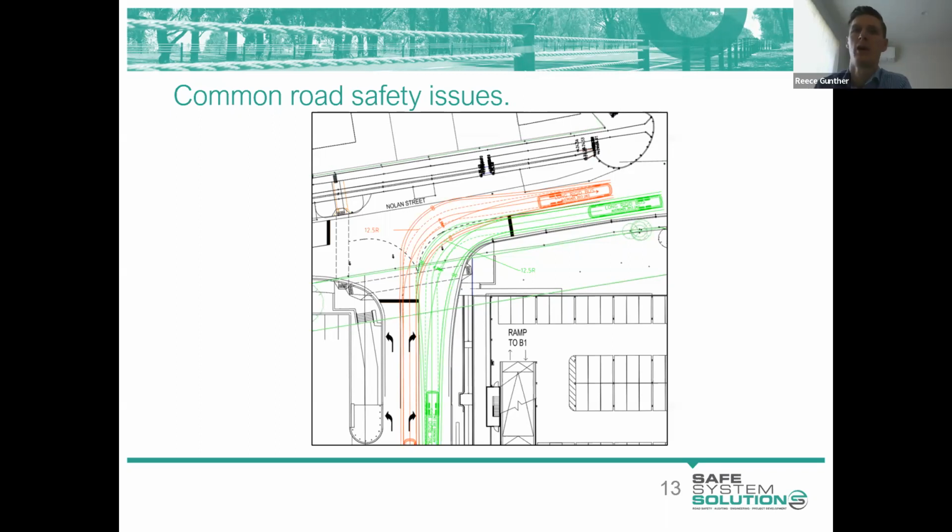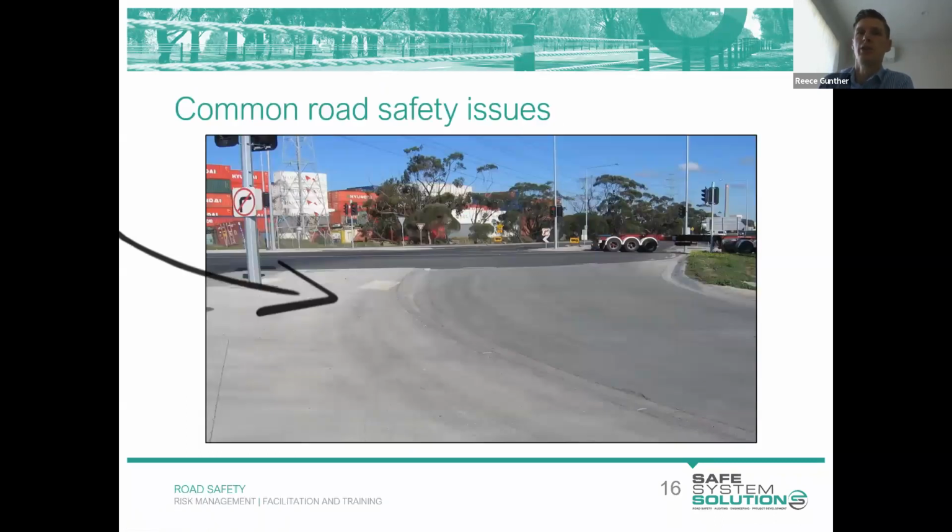When we're looking at swept path diagrams, it's also important to note that it's a requirement that the vehicle goes from lane to lane. So they don't make a funny maneuver where they go up and use extra space that may be above the intersection or shoulder areas and then maneuver back in. There is a requirement that the maneuver is performed lane to lane. Some of the issues as a result of not running your swept paths correctly, or having incorrect swept path analysis or adoption of a design vehicle, could be encroachment into areas, as we highlighted earlier, behind the curb and into pedestrianised areas.